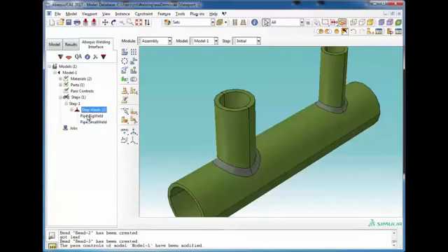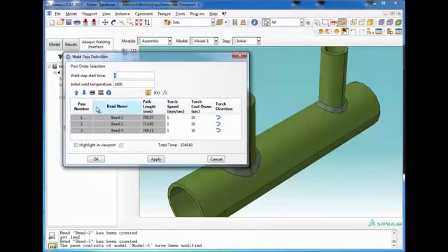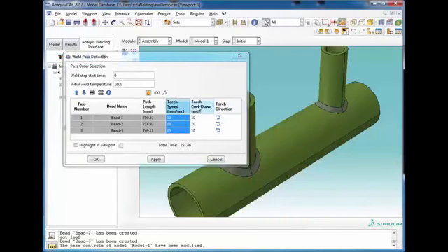So we've defined, let's just look at the big weld. For the big weld, we've got the 3 beads. The color gray represents things that you cannot modify or edit. So we have torch speed. If we want to change the torch speed, let's say to 10 millimeters per second, that's really moving. Then the torch cooldown time. The plug-in takes the path length, the torch speed, and the cooldown time, and calculates the total time to put this weld down.